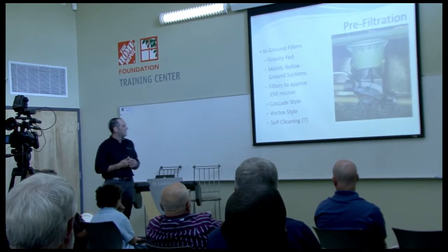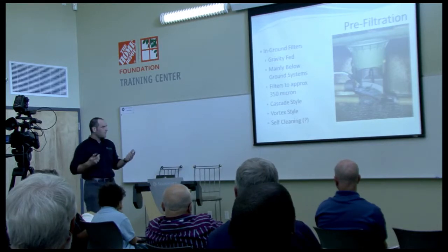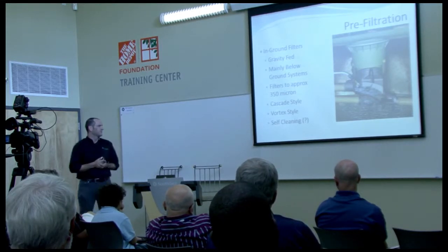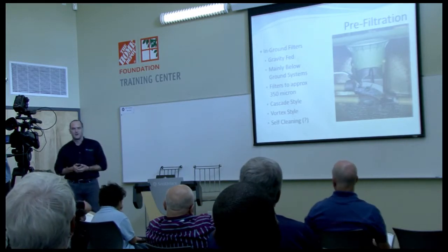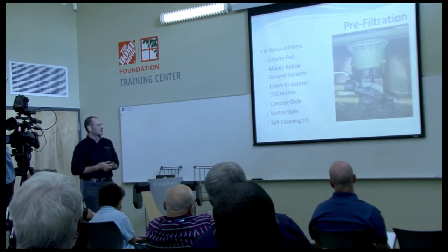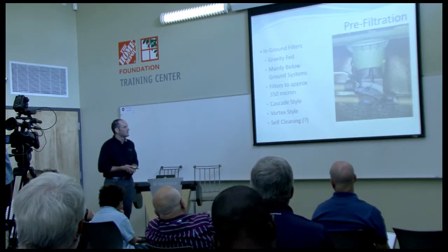There's another style, vortex style, where the water enters the filter and spins in a vortex fashion. It's the same basic principle, same filtration level. But again, these are probably the most common for commercial or even residential systems where you have below ground tanks, or even for some use with above ground tanks.